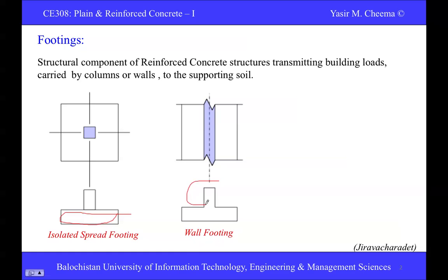If you see this elevation of the wall, this is a wall section, and here is the footing where the wall is resting. In normal observation here in local areas, you might have observed the wall footings are stepped. Maybe you have seen this in your previous classes, and when you go for foundation design or in your estimation and construction, you have this kind of step footings.